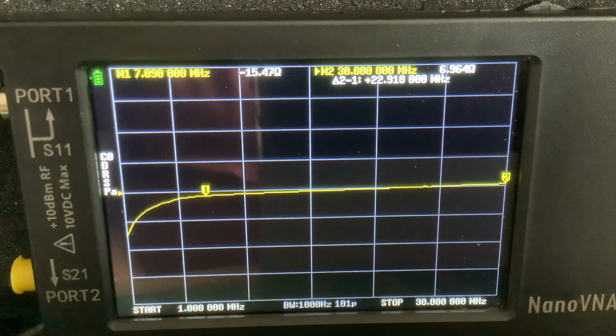But of course, it means we have got a much lower input impedance. You could fix that with some impedance matching, like a transformer or something like that. So it works, but as I said, no such thing as a free lunch when it comes to RF electronics.